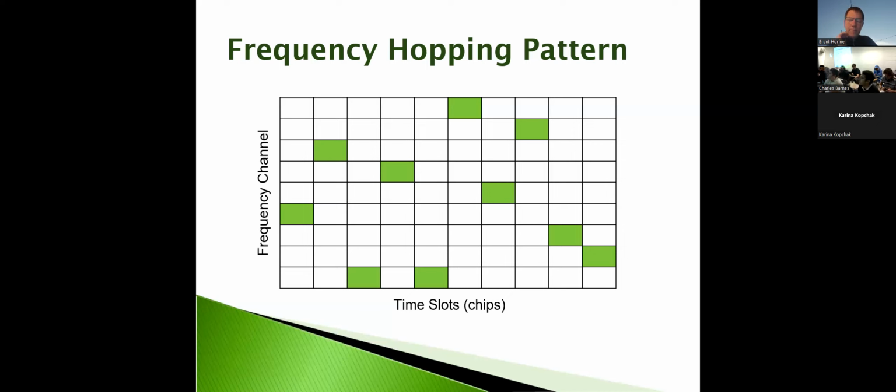Yeah, so basically you would take a single symbol, and then you would hop within that symbol. And yeah, there are some subtleties in how you achieve synchronization. This is why FSK is a little bit easier, because with quadrature amplitude demodulation, we need to do that coherently.